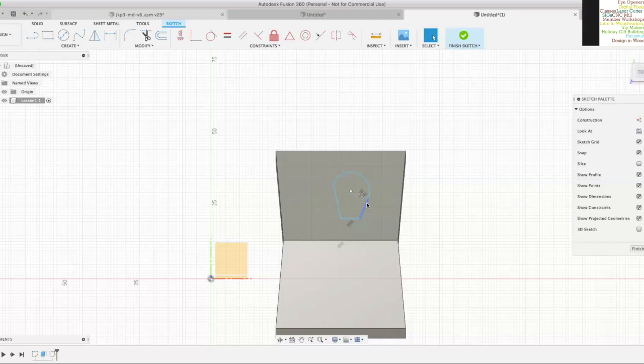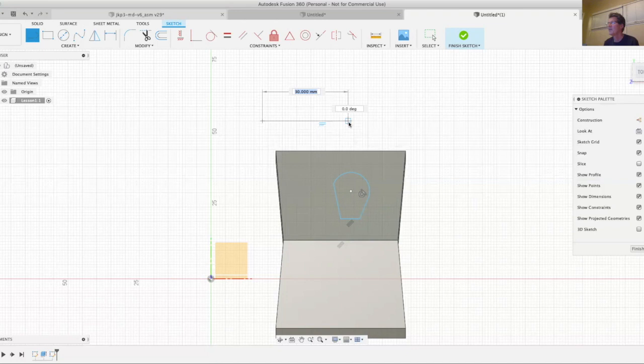Yeah, but if you wouldn't mind drawing one more real quickly so we can get that sequence of events. Yeah, okay, that's a good point. So I'm going to start with the line, one click, and then move, and it's creating a line. Now I make my click to complete that line, but if I now hold the button and drag, now I'm doing an arc, and when I release the button, it finishes the arc.